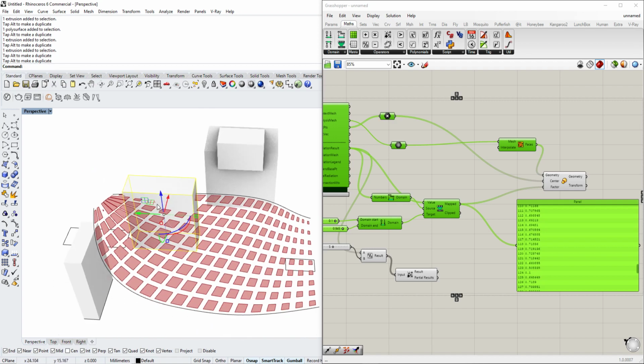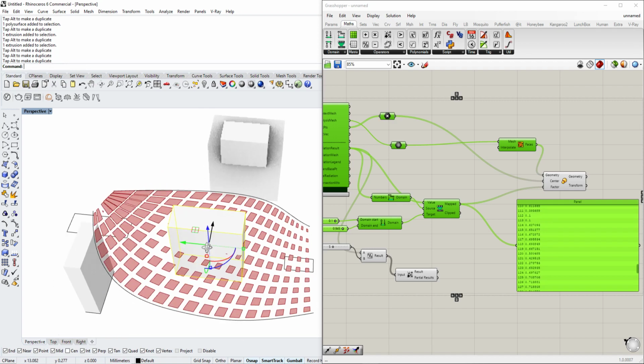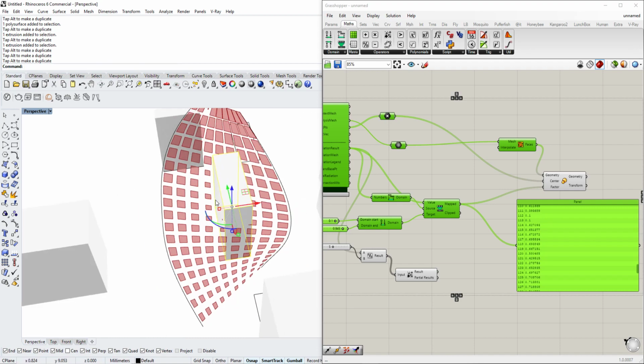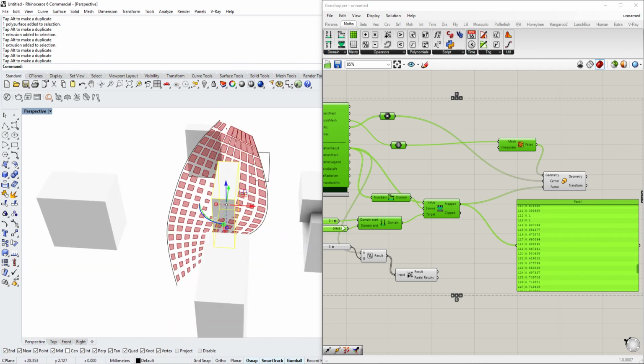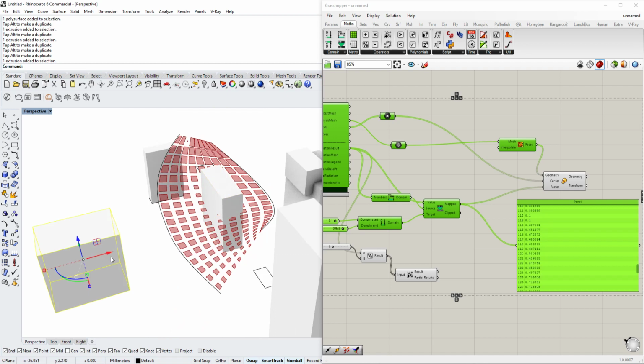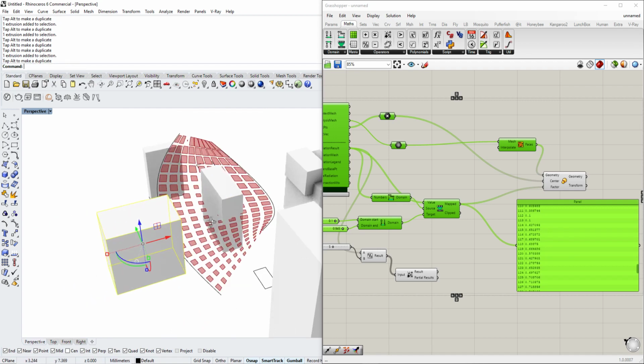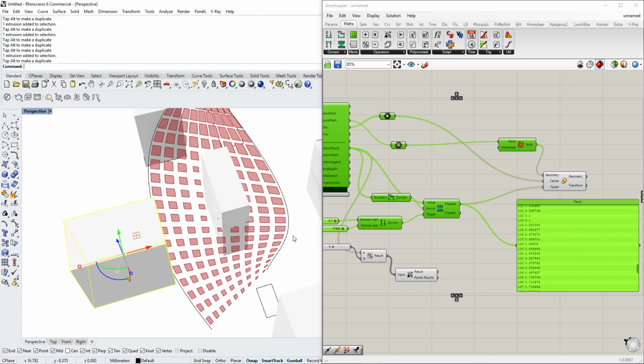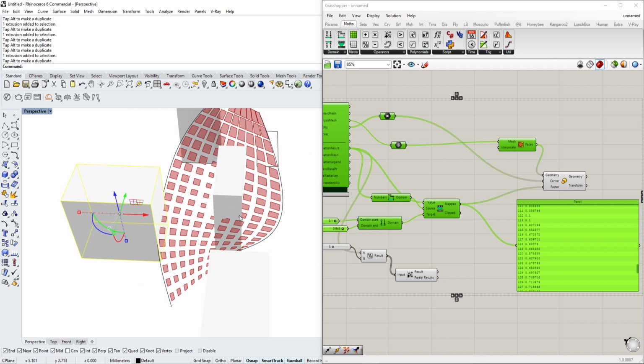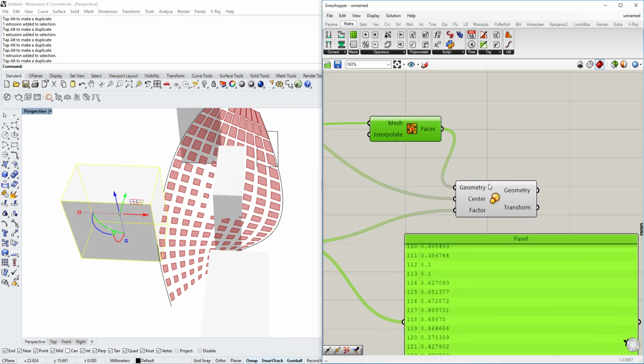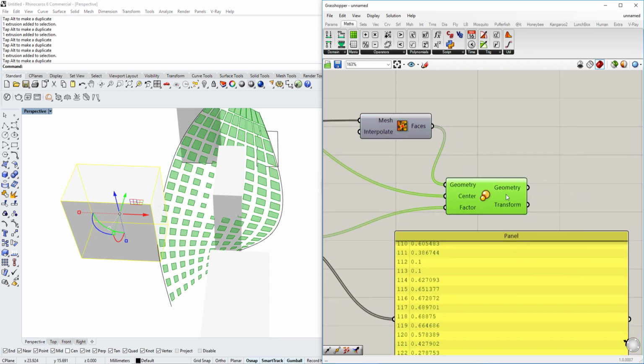Or if you want to do something a little bit less, or create shadow how you want it, you can do that. And the cool thing is, because you have the EPW file on the Ladybug side, you can put any EPW file for about any single country in there, and it gives you this result.